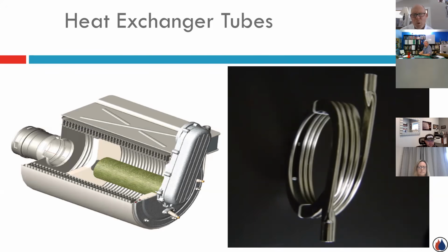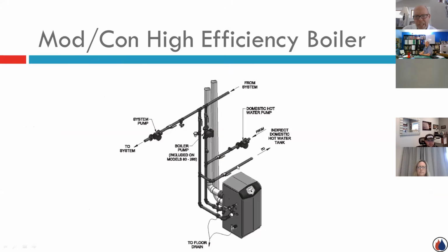Very, very different than the old sectional cast iron boilers that had virtually no pressure drop. So the manufacturers were concerned that they wanted to provide adequate flow through these tubes. So they said, look, the way we can ensure that to happen is we will provide our own pump and have our own tees close together so that this pump supports and takes care of the flow and pressure drop needs here. But because of the closely spaced tees, it does not inject any flow up into here unnecessarily. And conversely, the system pump is hydraulically isolated from the boiler plant.